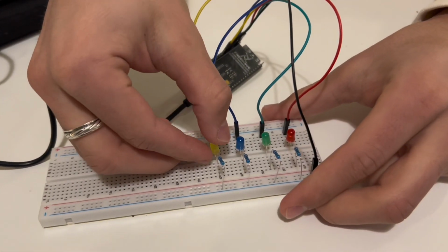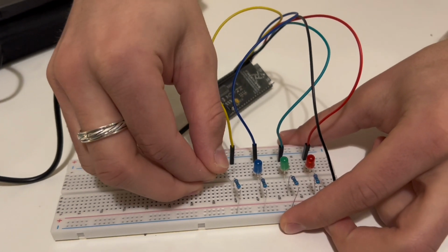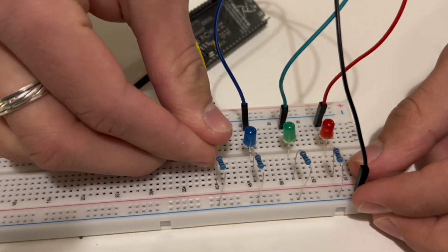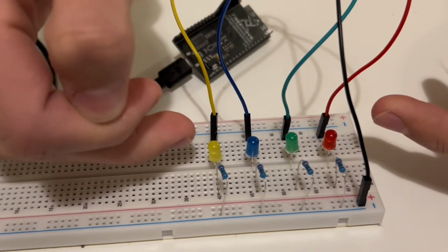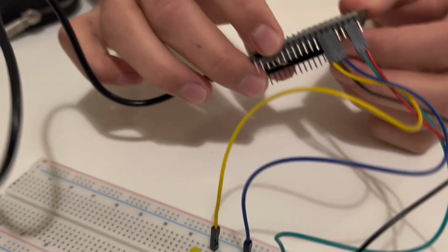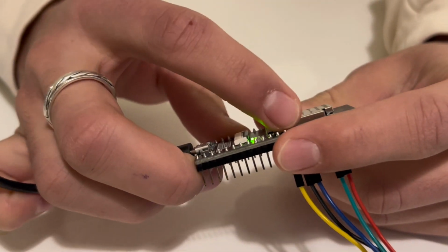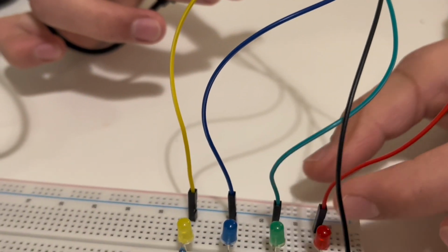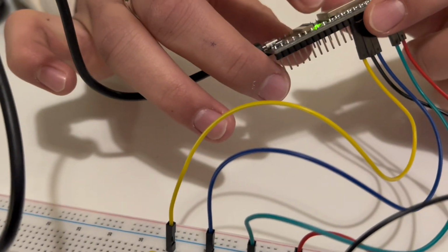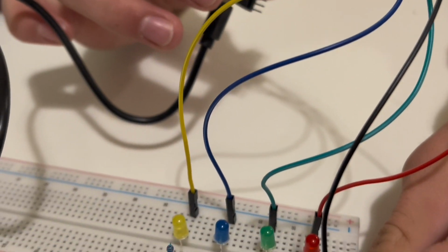For the LED lights, you put the ground pin towards the resistors. As you can see, here we have the ground cable, and the ground cable is to the side of the resistor, so you need to put the ground pin towards the resistors which are connected to the ground pin. On the microcontroller, I like to use numbers 19, 21, 22, and 23 for the LED light cables. I like to color coordinate them so I don't get confused. Between these numbers, there's the G and D pin, which is the ground pin, which I connected to it.